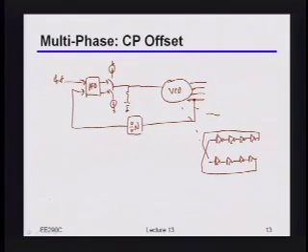Okay. So the basic idea is if I can just hack it so that somehow this phase over here changes, and changes in some controlled way, then actually I can make it so that all of these phases move together, right? Because the feedback is going to force one of these phases to track with whatever offset I introduced. But then all of the rest of them, because I know it's a ring oscillator, are all just directly related to the position at which I put that one nominal phase in the first place, right? So conceptually, does that make sense to people, in terms of the trick I'm trying to play?